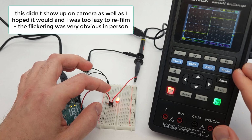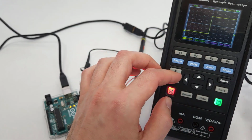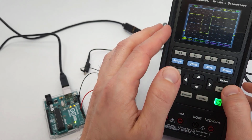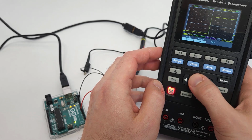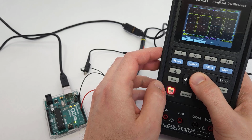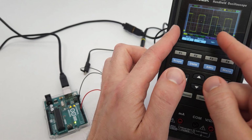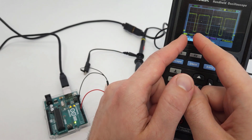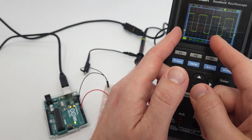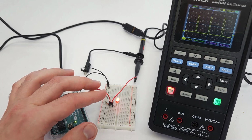So I just powered my oscilloscope back on, and I didn't change the scaling at all. So the time axis scale is still the same. And you remember before we could see multiple periods of this square wave, but now I need to zoom way out to be able to see multiple periods on this graph. So the duty cycle is still oscillating between 0 and 100%, but the period between each oscillation is now bigger, and it has gotten big enough that, again, it's not showing up great on the camera.